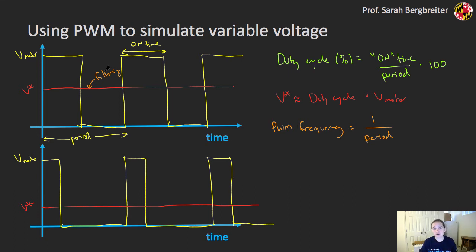Right, so I'm going to have to make sure that this frequency is such that I'm at a higher frequency, or my period is smaller than those time constants, so that I don't get appreciable turning on, turning off behavior. And typically, you can use a fairly wide range of frequencies for most of the motors that you'd encounter. So something at a couple hundred hertz would probably be sufficient, all the way up to tens of kilohertz.